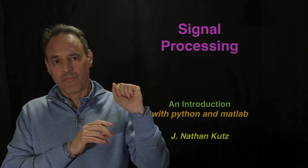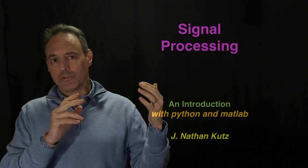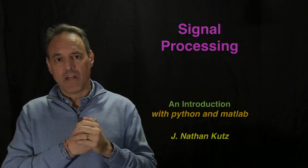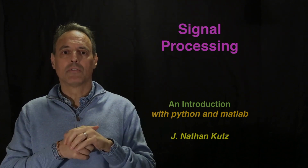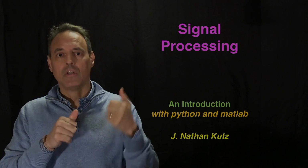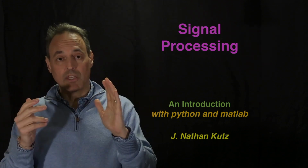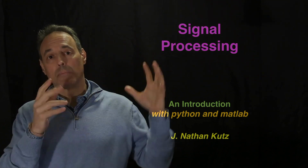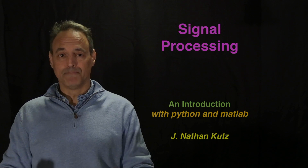Because once we know how it responds to a fundamental kick, all of the solutions are a summation of that fundamental response based upon where you kicked it in time. So just understand that it's a superposition of those fundamental kicks shifted potentially in time from where the kicks are happening. That's going to be the generic representation of any solution to our LTI system.